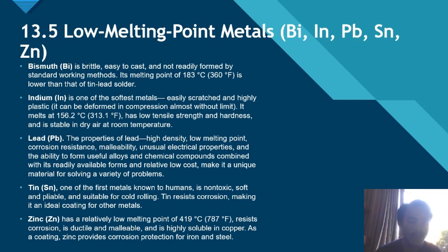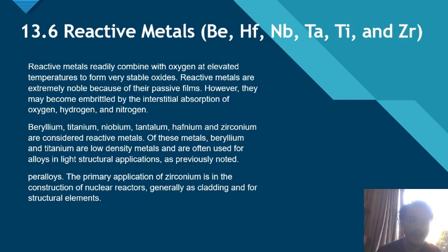And zinc has a relatively low melting point of 419 degrees Celsius, which is like 787 degrees Fahrenheit. It resists corrosion, is ductile and malleable, and is highly soluble in copper. As a coating, zinc provides corrosion protection for iron and steel.